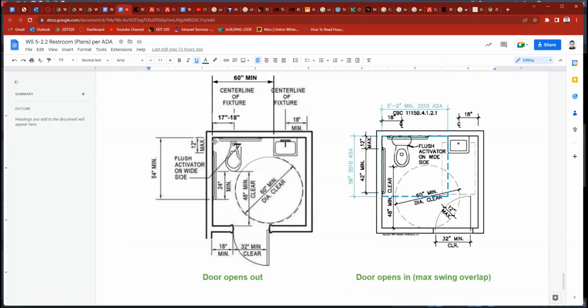It could be one straight L piece, but the edge of that grab bar must be 54 inches from the back wall. And how do we get to the 54 inches? Because of 12 inches and 42 inches, that gives us the 54 inches. So we need two pieces. The backside is supposed to be, I believe, 36 inches.